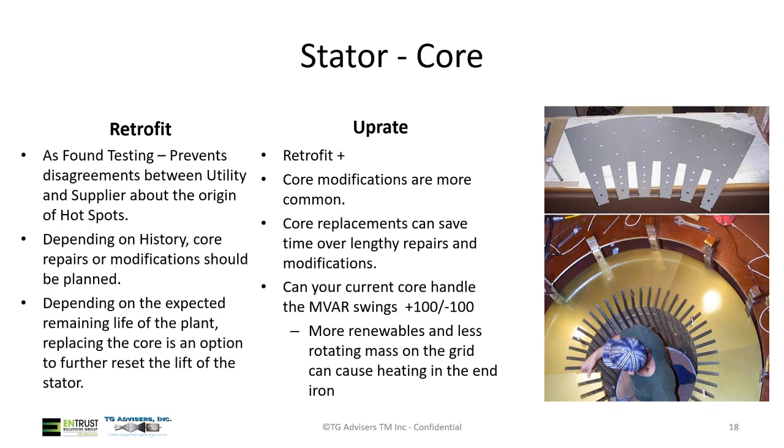The uprate considerations: an uprate is a retrofit plus. It's everything included in the retrofit plus a few other things, and core modifications are a lot more common with an uprate. You might have more load on your rotor, which could end up with higher end iron heating or body iron heating.